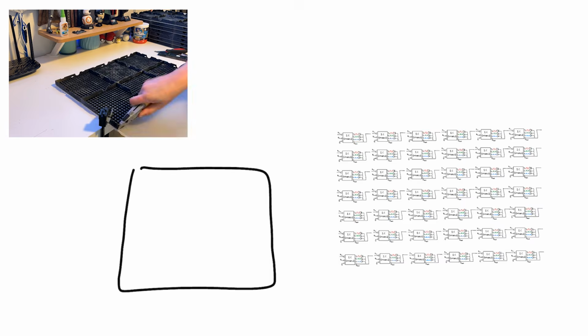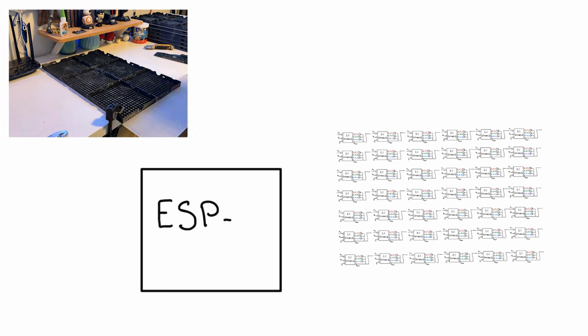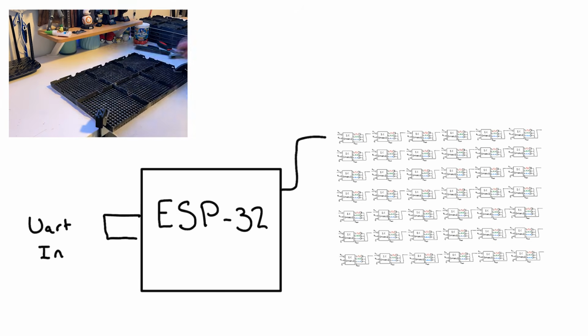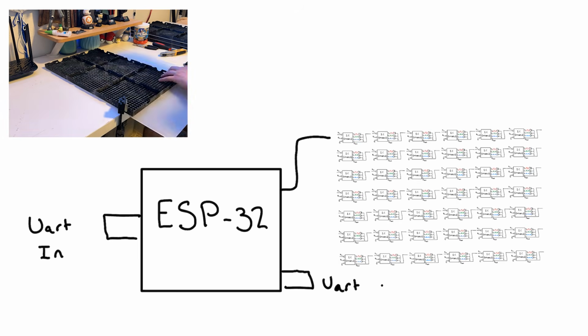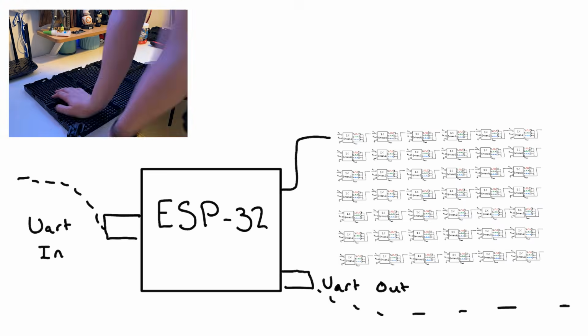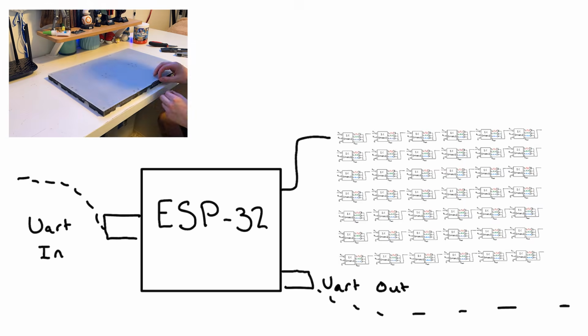The ESP32 on my dev board works in a very similar way. It gets pixel data from the serial 0 port through the first headphone jack, then sends any extra data out of its serial 1 port through the second headphone jack. Theoretically, I could connect an infinite number of panels together this way, but it will eventually get really slow.